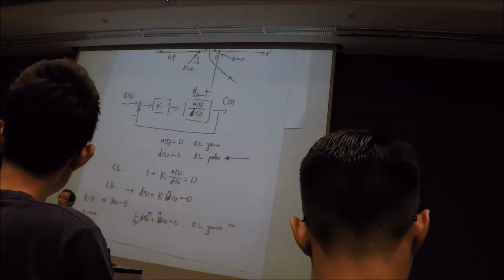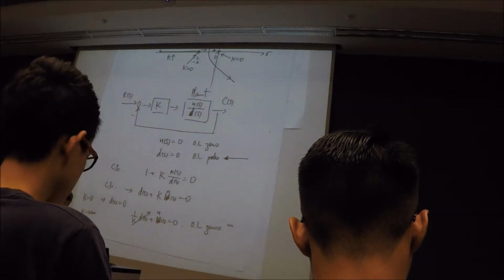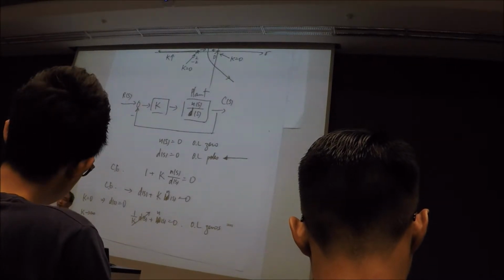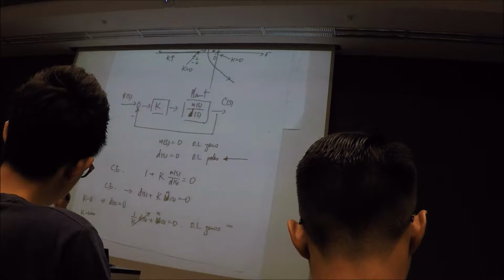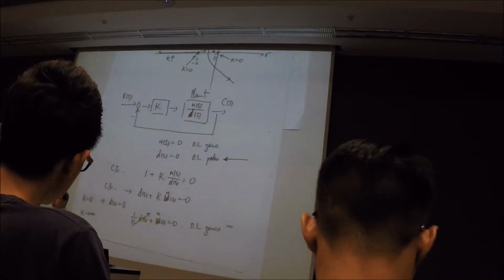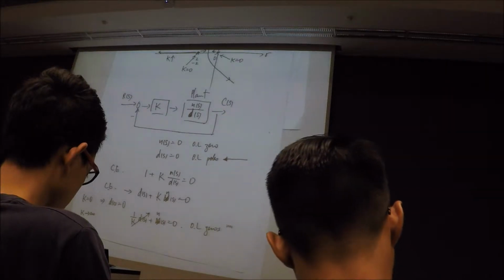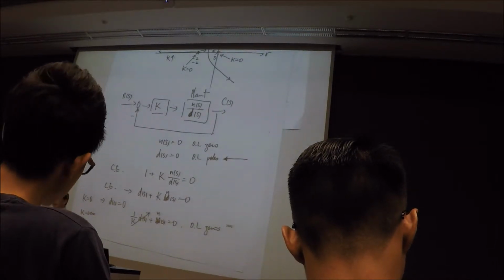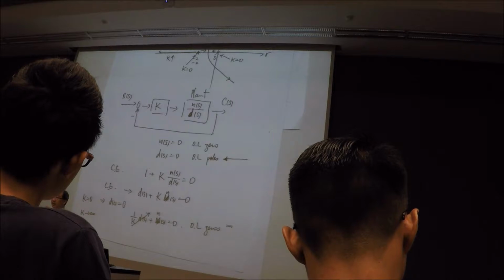If your transfer function has 1 finite zero and 3 open loop finite poles, and as we mentioned, a pole has to go to a zero, then what happens to the 2 poles? One pole can go to the zero, the other two poles have to approach what we call the infinite zeros. Okay, and that is how we will introduce along which direction these 2 poles are going to be approaching your infinite zeros, your open loop infinite zeros. So there is a direction that the pole will basically be approaching.